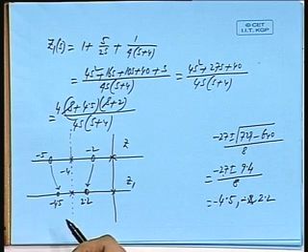That means the pole that you are weakening will be attracting the zeros from their earlier positions towards that particular pole itself. So the movement of the zeros are known. So once you know this, then the problem is simplified. You know which zero is to be created by weakening which pole.